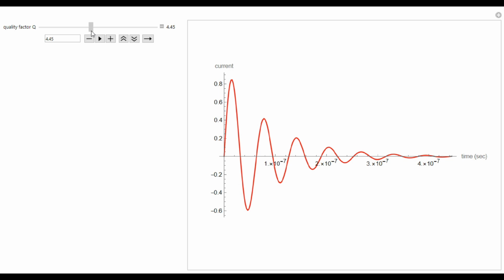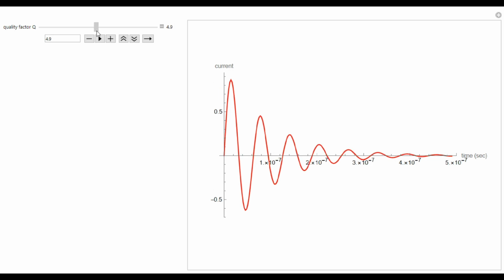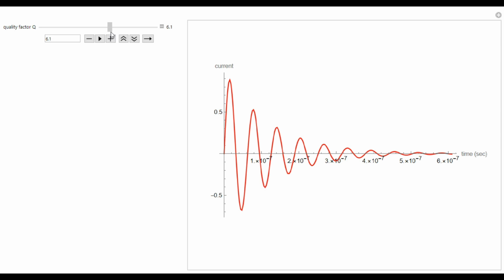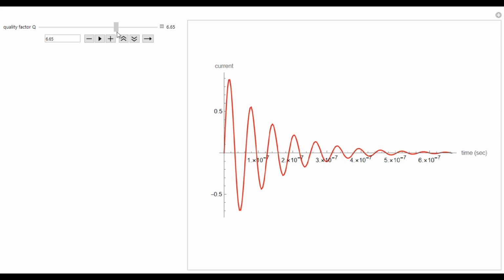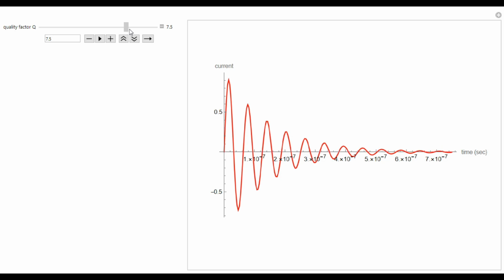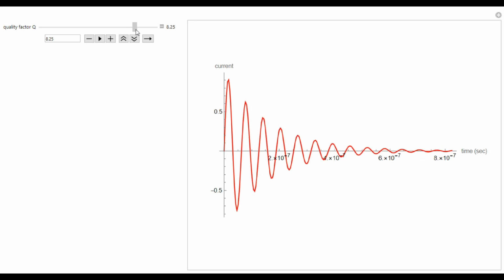Real-world analogy. Think of a car's shock absorber. If it's critically damped, the car settles quickly after hitting a bump without bouncing up and down. Critical damping is often the goal in engineering systems because it provides the fastest response without oscillations.